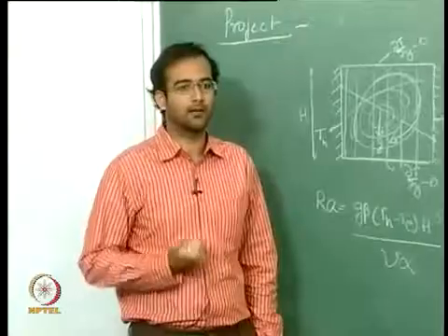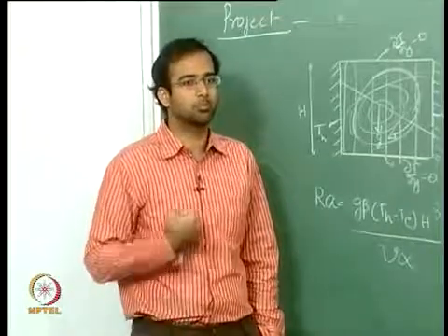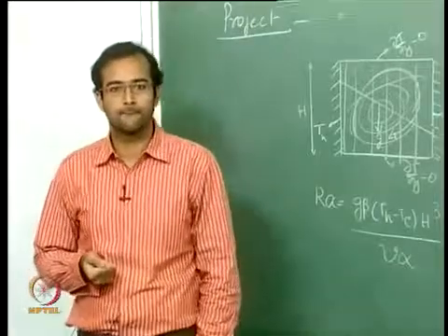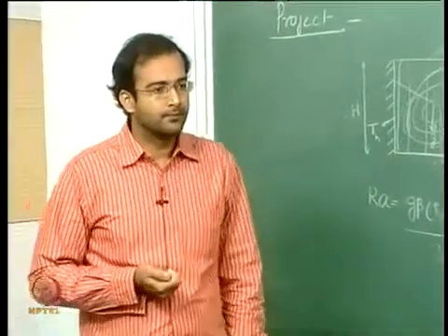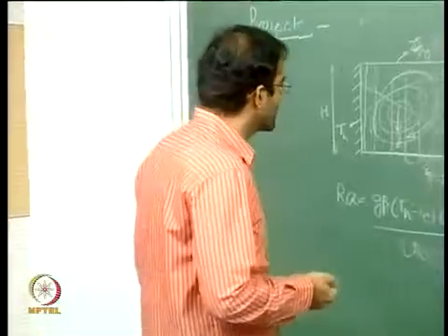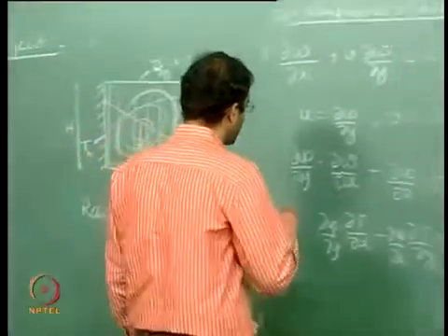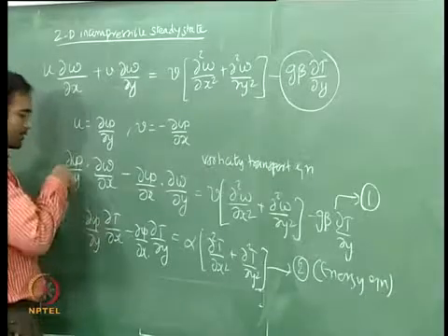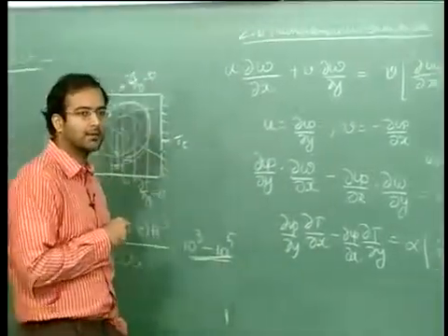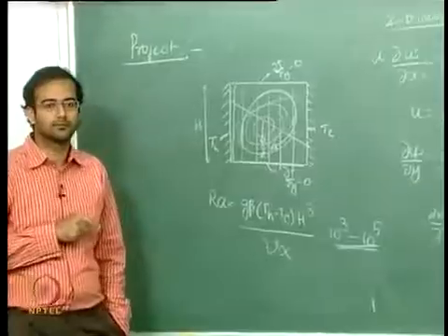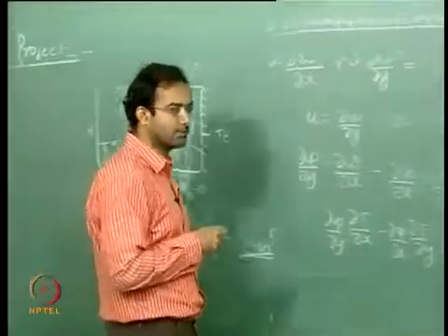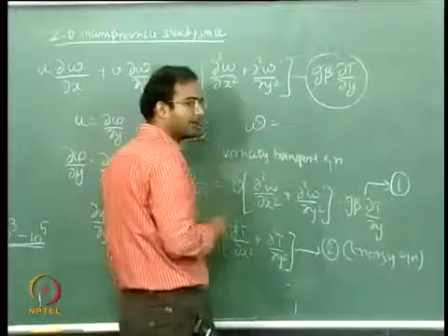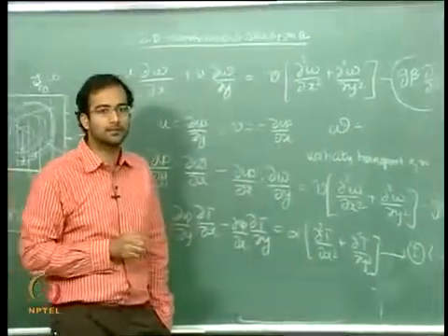Do you have enough equations to solve for all the variables? So this is the governing equation for vorticity, right? And this is the governing equation for solving temperature. But what is the equation for getting the stream function? So there we use the definition of vorticity. Okay, you define your vorticity. How do you define vorticity in 2 dimensions?